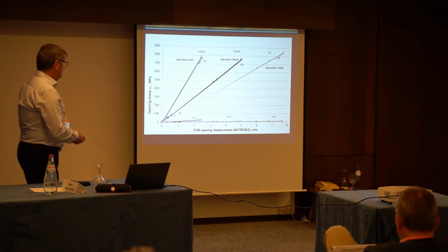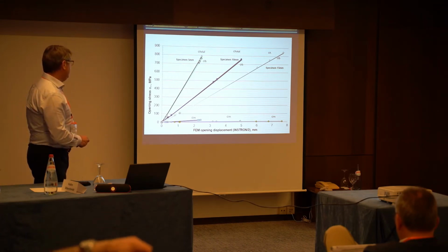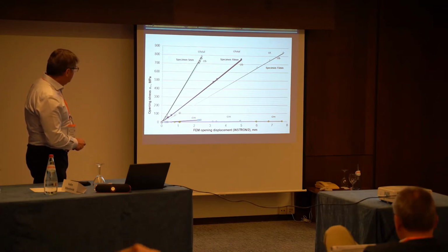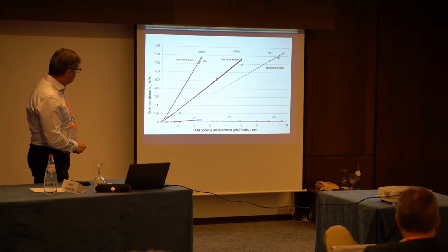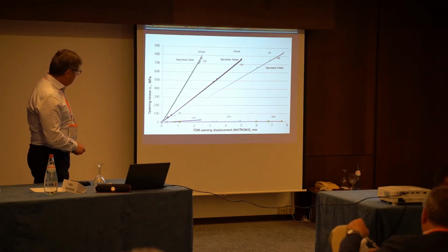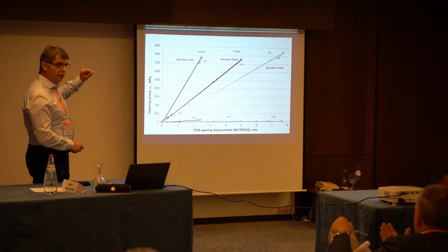But now we need to calculate the stress. The stress we took from the model, and for 5 millimeters you have this loading path. And here we have that our load is mainly the total load, but it consists of two parts. It consists of the membrane strain, so for tension, and this one here, the light blue, is the bending. B is bending. And the total is just the superposition of membrane and bending for this small point.